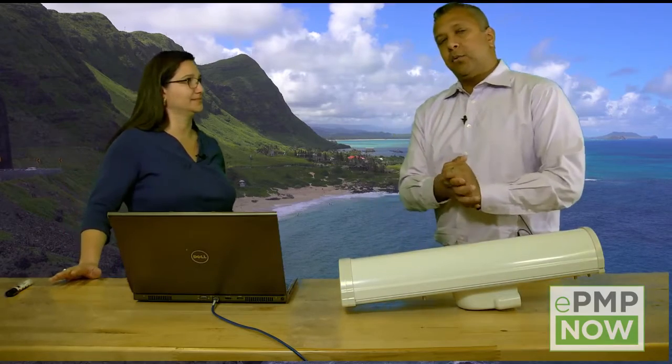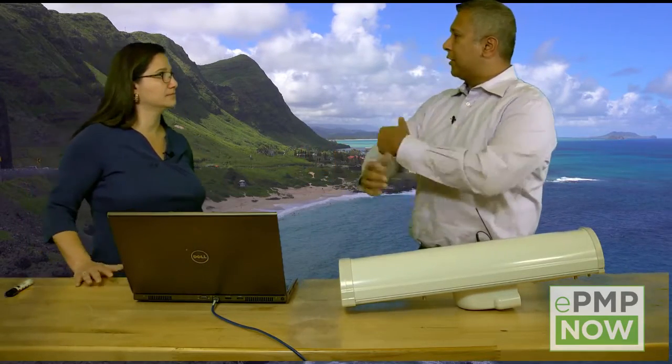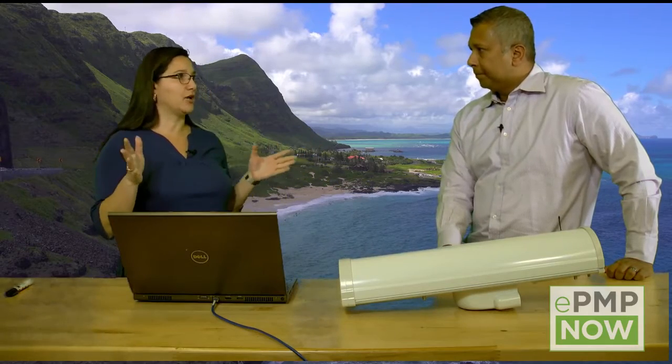So, Lucia, one of the first topics that we emphasize a lot at Cambium Networks is the concept of front-to-back ratio. Yes. And we have videos that talk about it, but how would you like to give us a little lesson on what front-to-back is and why it's important? So, first of all, I want to talk about the fact that this is a directional antenna. Okay, right. So what does that mean? An omnidirectional antenna would be an antenna that sends the signal strength in all directions. Okay. But the directional antenna focuses the energy in only one direction.